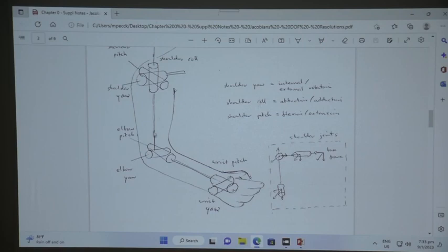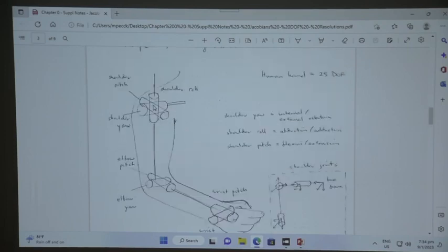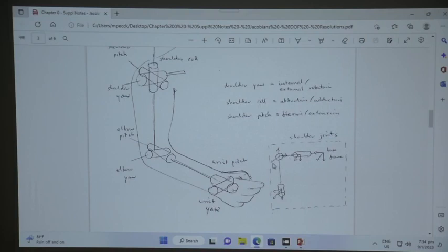So you see, this is a drawing of your shoulder, and then you may actually depict the drawing of the joint in this manner. So you have a single frame attached here, and then you have the base frame over here. So you have 3 that join together, but you can expose them, and then from here you can see that they consist of three 1-degree-of-freedom joints. So this is this, this is this, and this is this.